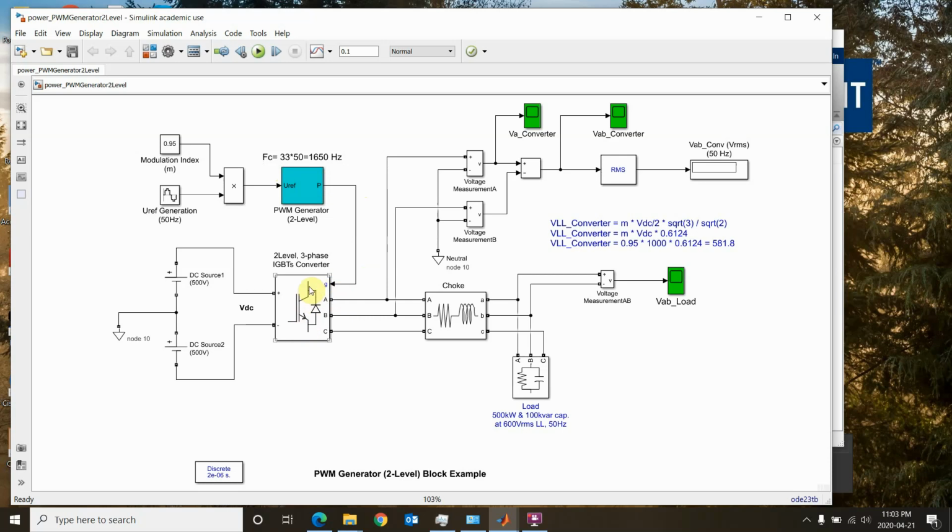And then over here you have some transistors and some diodes that, based on this PWM signal, would convert this DC voltage to PWM AC voltage, whose pulse width is variable.